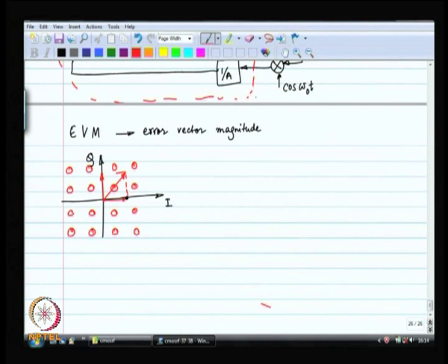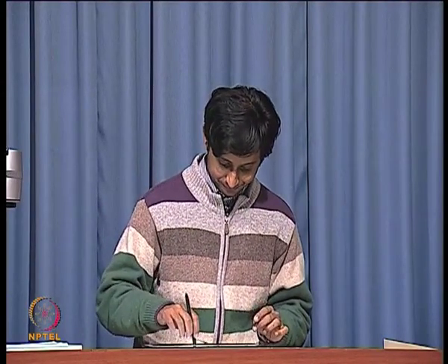So, this is called 16 QAM. There are 16 symbols, 16 possible symbols. At every instant of time, you are actually sending one of those 16 symbols, which means you are sending 4 bits at a time. So, it improves the data rate of communication. So, 16 QAM is used quite often in modern systems, modern cell phone systems.